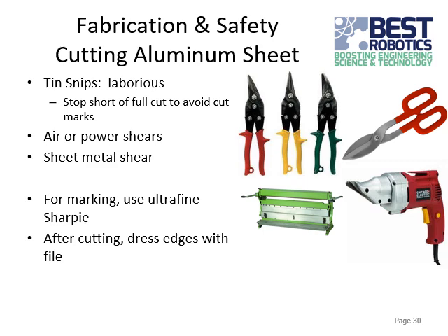And after you've cut it, and this goes for the previous things too, I should have mentioned, you want to clean up the edges. With the metal, you can use a metal file to clean up the edges so there aren't any sharp burrs on it. With things like plastic or wood or whatever else you're cutting, you can clean it up with a piece of sandpaper. You can use some of that for metal too, to soften the corners a little bit. But a file works pretty well for cleaning up the metal edges.